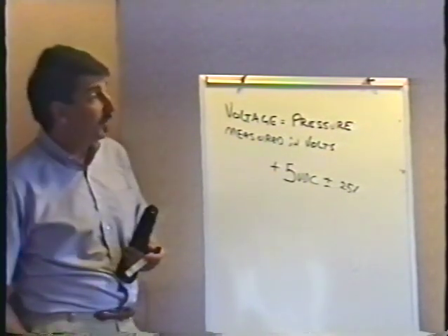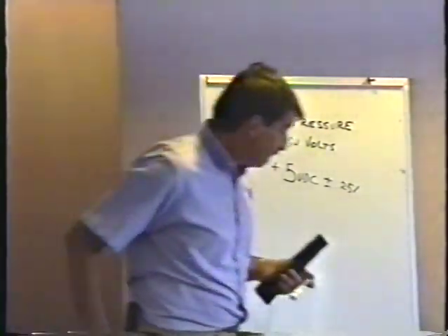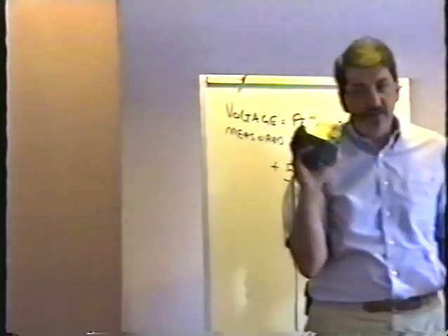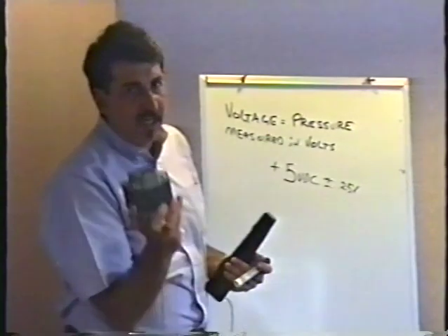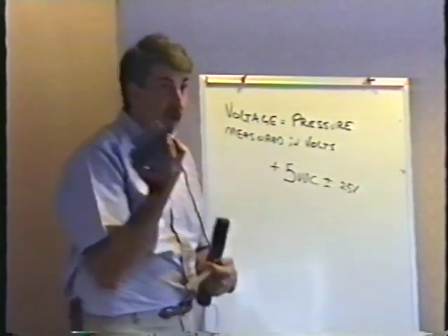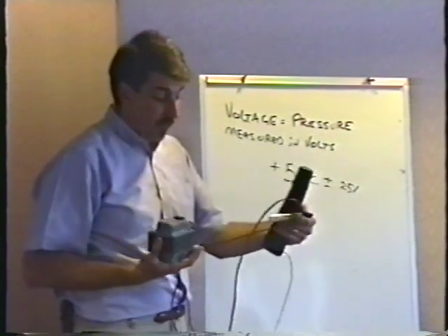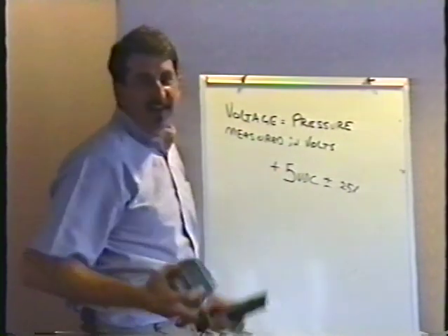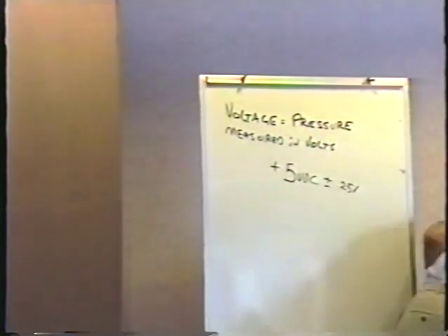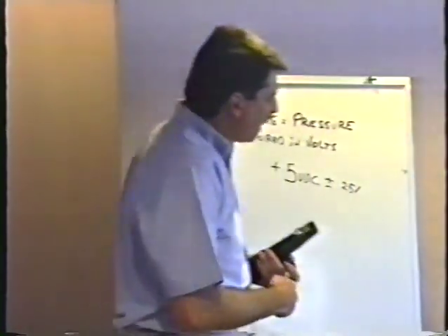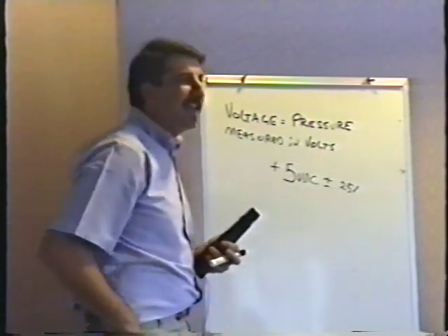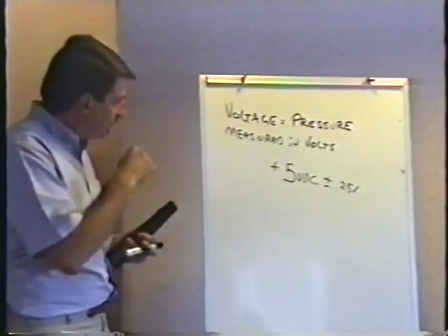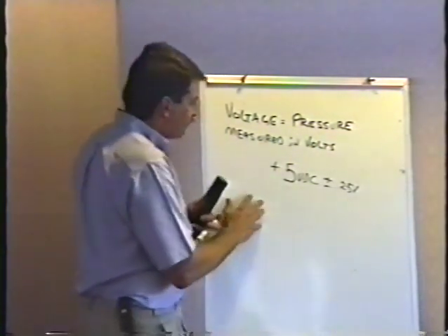In fact, we'll talk more about this. There's a type of transformer that you'll use in every game called an isolation transformer. It's a safety transformer. Without this isolation transformer, there's a possibility of putting 120 volts on your logic board. This is a really common problem in Mexico, apparently. They go, well, I don't need no stinking transformer, and they don't put it on there and blow stuff up. This thing is nothing more than a converter. Well, we'll talk about it in great detail coming up. It's an isolator. It isolates everything from the AC power line. I'll give you the straight poop as we go through this. I'm just trying to introduce you to some different terms now.